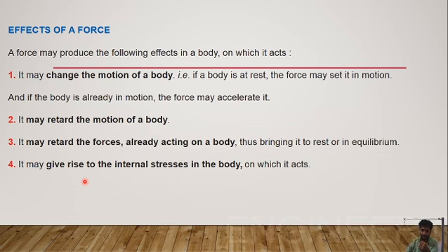So that we will study in the higher semester. Actually, stress is a term used by mechanical engineers. It is the resistance offered by the body against the applied force. We are applying the force on the wooden block, but we cannot see the wooden block breaking. That means the wooden block is resisting the applied force. That resistance offered by the wooden block is called the stress. So it's the fourth effect of a force. Sometimes force cannot produce a physical change, so it will produce an internal stress.